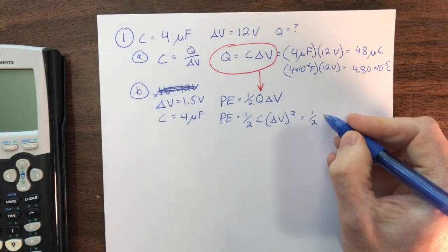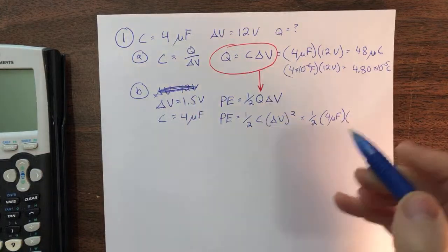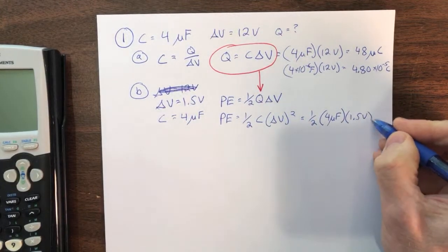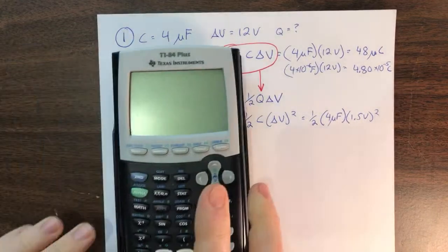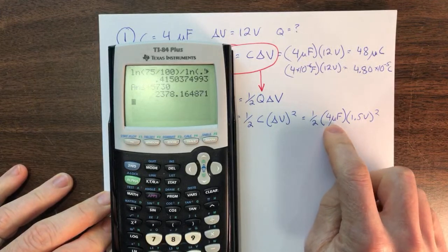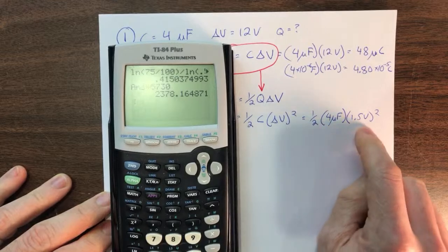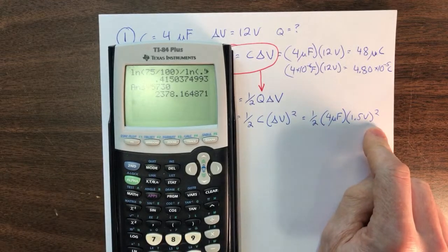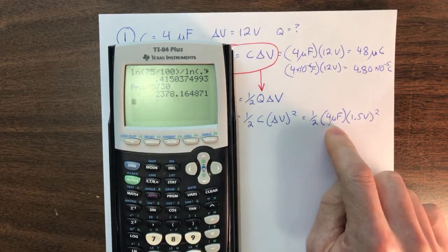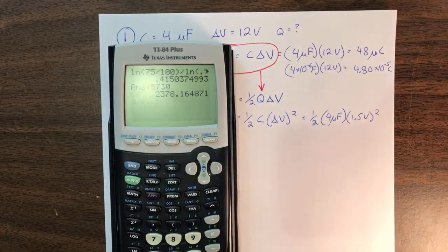So that's going to be 1/2 times the capacitance of 4 microfarads times, in this case, 1.5 volts squared. And let's go ahead and do that. You have to be careful if anything in here is, for example, squared. If you have an exponent over here, then you're going to need to make sure that you square that prefix too. In this case, you don't have that case. It's the 1.5 volts that are being squared, so you don't really need to worry about that situation here. And so you can just carry that prefix forward. But you do need to be careful about that when doing this math, that sometimes if this is squared, then that's going to affect things.